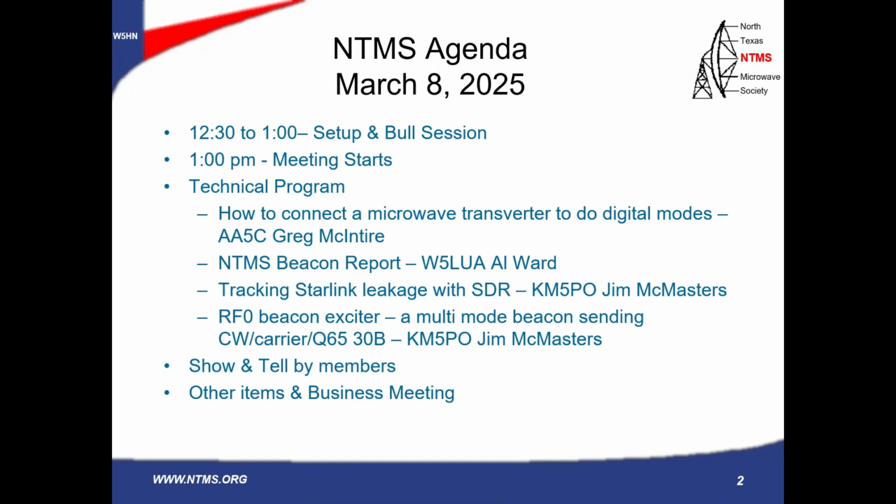But the old N1JEZ, I think it was, I use that as the reference. It's very simple and very cheap, but it does the dividing down and does the comparison and locking with a 100 kilohertz signal. And surprise, surprise, there were 100 kilohertz carriers all up and down 24 gigs, which was quite a surprise.